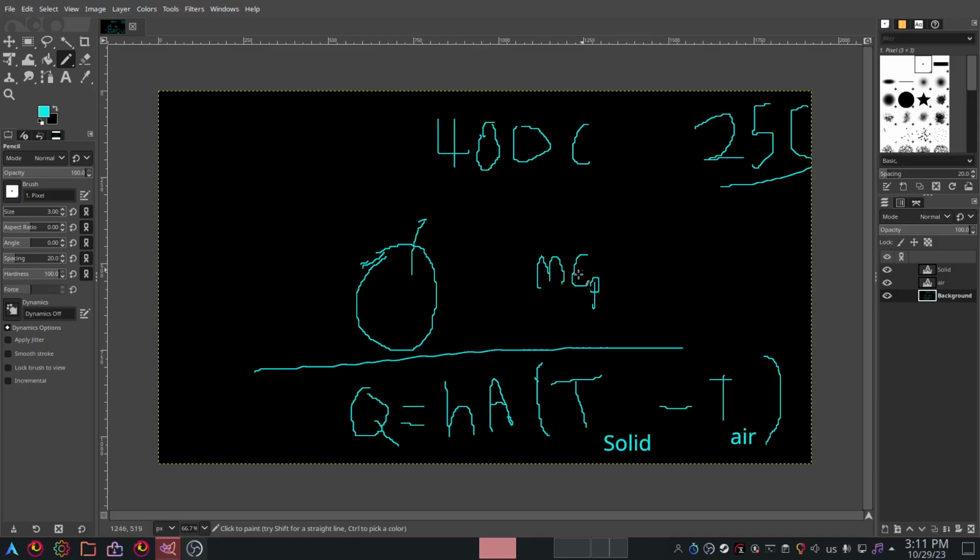So the ball temperature is uniform and constant. We call this a lumped heat capacitance. The rate of change of this ball temperature is described by m c_p dT/dt, where T is the temperature of the solid.